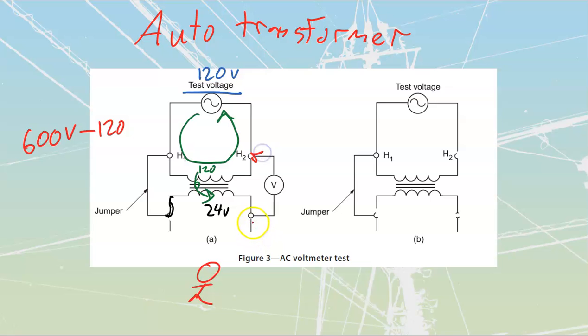Good quality voltmeters should have a high impedance coil, so it's not like a short circuit or anything like that. I'm just measuring across here. If I were to measure 96 volts on here, that's going to indicate to me that this is a subtractive transformer. Same test over here, the same transformer, here's 24 volts, and when I place my meter across this one, I'm measuring 144 volts. That's going to become an additive transformer. And I can mark it as such, okay?